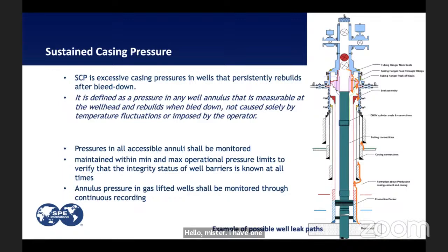Why is this cement not up to the surface? Yeah, so cement by design is not required to be at the surface. In most of the standards, it is mentioned that it is mandatory, a shall requirement, for the cement to be at surface only for the surface casing, because we have aquifers behind it. And for the subsequent casing, it has to be by design above the shoe of the previous casing, so all the barriers are there.